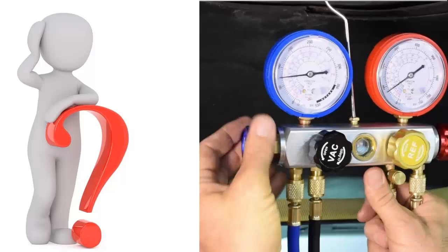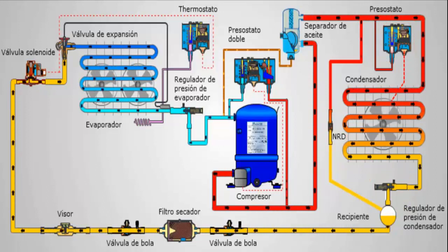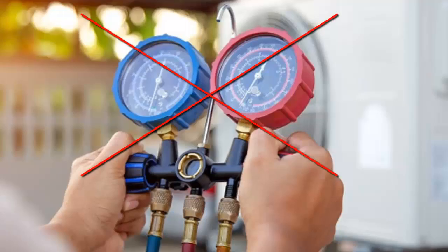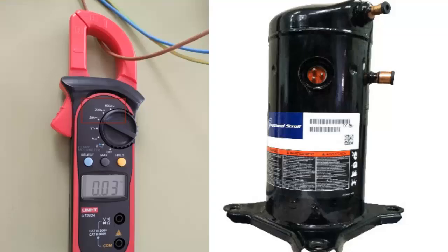In this video, we are going to explain how to determine the lack of refrigerant gas without using the manometers. Let's start by saying that an essential tool to start diagnoses in refrigeration equipment is the clamp. The perimetric clamp allows us to measure the electrical consumption of a device without the need to intervene directly inside it. We can do the measurement using an external power cable.